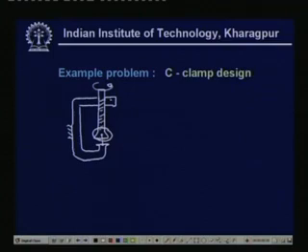Now, you see, whenever we want to give a pressure, we have to turn this screw and the whole body turns, but we do not want this surface to turn so abruptly. So, therefore, we need to stop this turning motion when it gets transferred to here, and this is done by means of what is known as a collar or thrust collar.